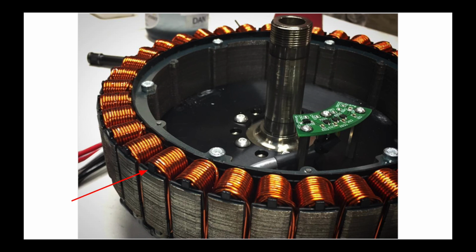Several forms of insulation are used to protect the coils, including these plastic cages around the stator teeth. Other common methods are using Nomex paper or dipping the whole stator in a light resin before winding. Nice, thick, solid core wires keep resistance down and provide a good fill factor, looking to be somewhere in the mid to high 60% range.